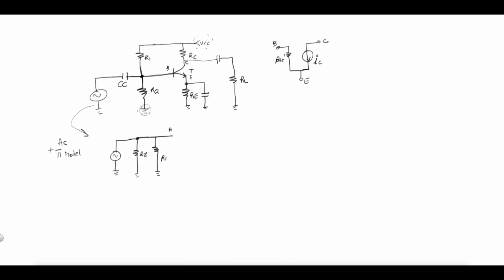It's not any different, except now the emitter is to ground, since this is a bypass capacitor, let's call it CE here. At whatever frequency you picked as your operating frequency, hopefully that's what you intend to do, you are shorting RE. That's for the DC part of your circuitry as far as the Q point. So that means at B, at the transistor, I still have this resistor right here to ground, since this is going to be ground for this circuit.